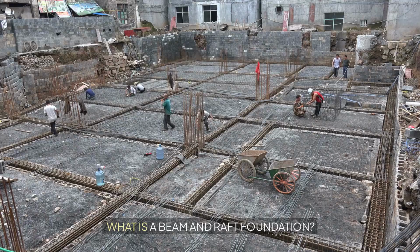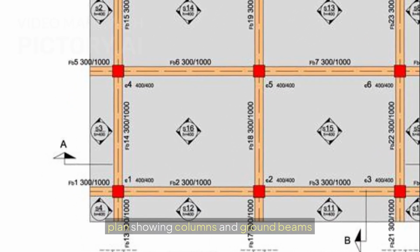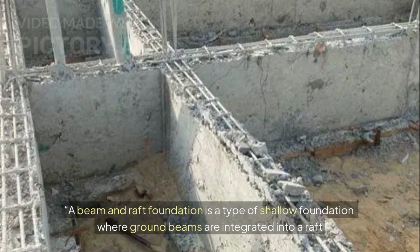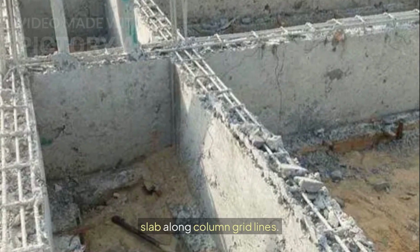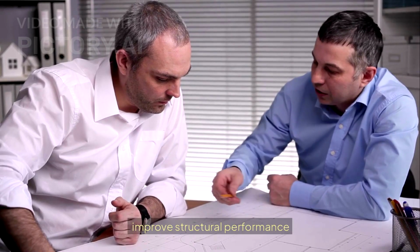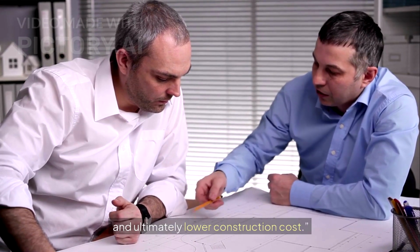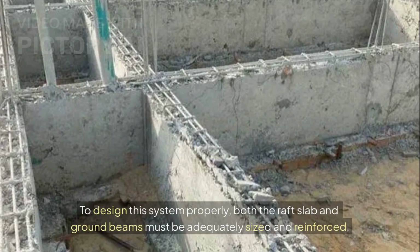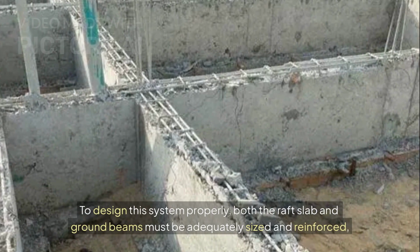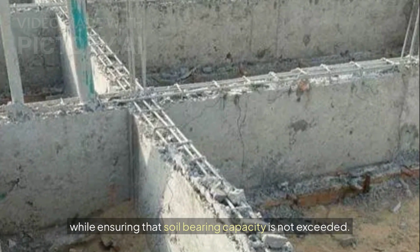What is a beam and raft foundation? Plans showing columns and ground beams. A beam and raft foundation is a type of shallow foundation where ground beams are integrated into a raft slab along column grid lines. The aim is simple: improve structural performance, reduce slab thickness, and ultimately lower construction cost. To design this system properly, both the raft slab and ground beams must be adequately sized and reinforced, while ensuring that soil-bearing capacity is not exceeded.